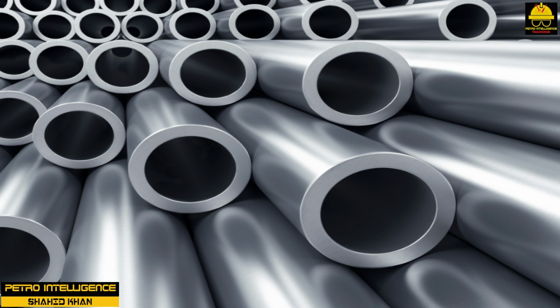These steels still retain much of the ductility, toughness, and weldability of low-carbon steel but require more extensive and careful heat treatment when welded. The chrome alloys are used in pressure vessels, piping, furnace tubes, and exchangers operating at high temperatures and pressures. Some of the processes used in refining and chemical plants employ hydrogen at high temperature or high pressure or both. Low-carbon steel normally becomes brittle in this service above 500 degrees Fahrenheit or 260 degrees Celsius.